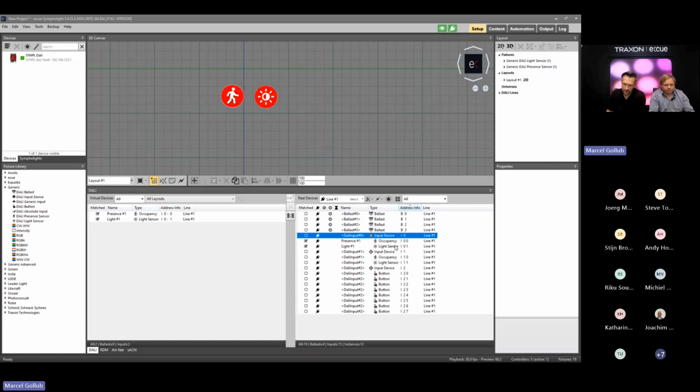Below this, you have instances. The benefit of DALI 2 is that you can connect up to 64 control gear plus 64 input devices, and each input device can have up to 32 instances. This is a huge number of possible control interfaces, only limited by the maximum power of the DALI bus.